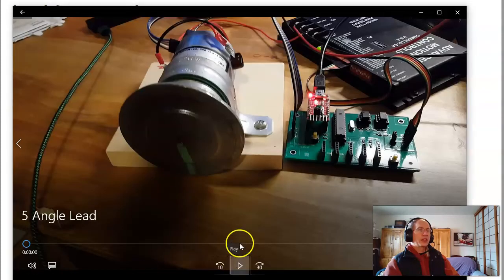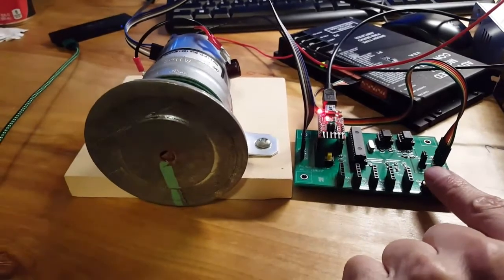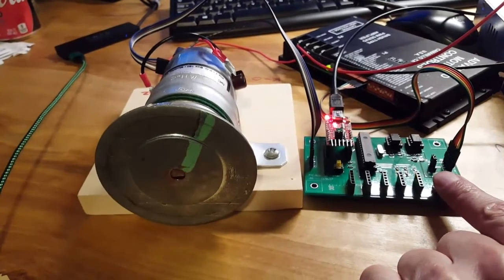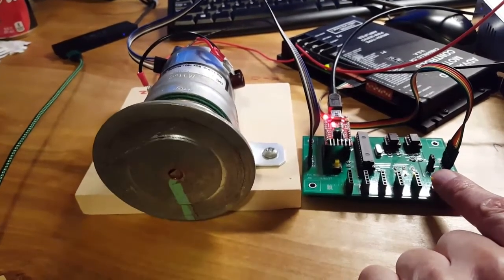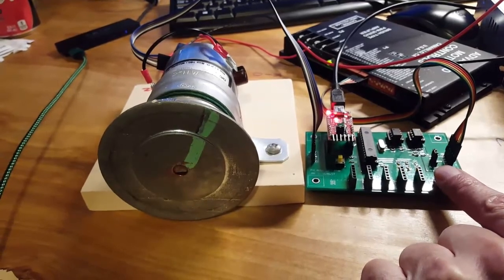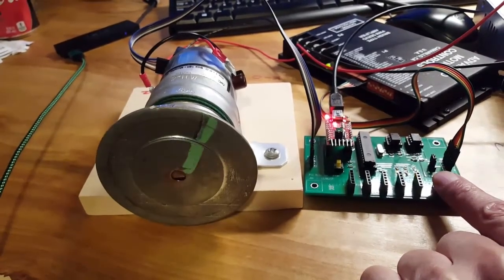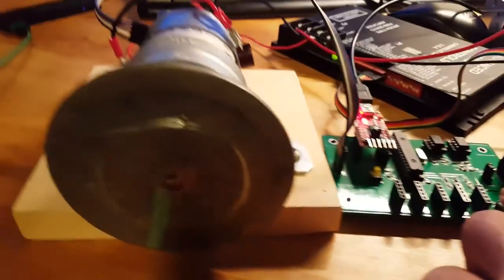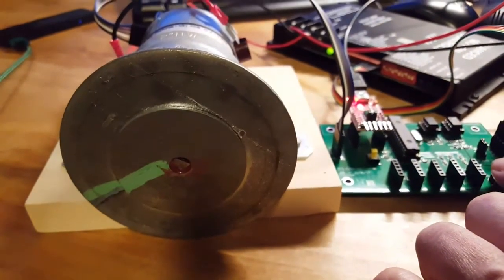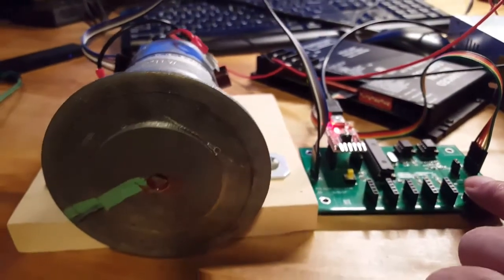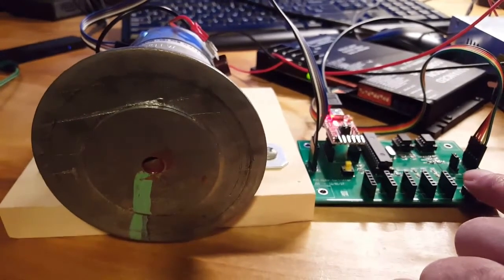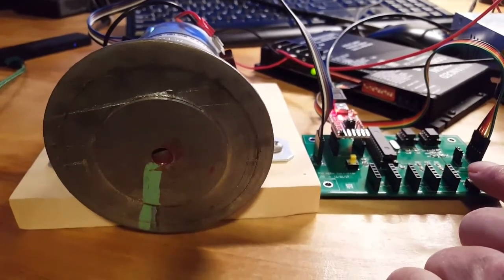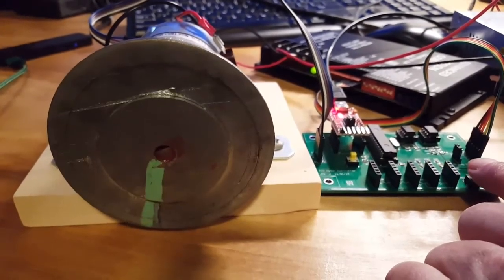And to see what that looks like in hardware. Here I have position control with a lead compensator, a digital lead compensator. I've placed the pole at 0.6 in the z-plane, and now I'm actually getting decent tracking. It's going between 0 and 5 radians. Here's an example of the lead compensator with position control going between 0 and 1 radian. And in this case, I've got the damping ratio set to 0.7, so you get a little bit of overshoot, and that's what you're seeing.